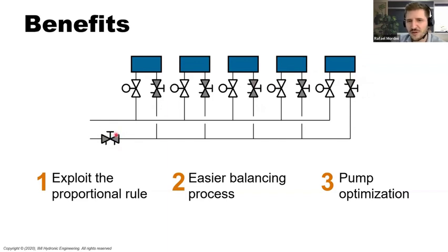You don't have to close this valve. In fact, sometimes this valve doesn't even exist on the system. You just finally were able to identify how much overflow you have on your pump, because now the entire system has like 15, 20% of overflow. And then you decrease the pump rotation. You go on the VFD, you start to decrease. The pump doesn't need to be running at 60 hertz. You find out that you just need 55, 54. And then you create your set point. And that's how you do a perfect balancing. You save the energy there doing your balancing.